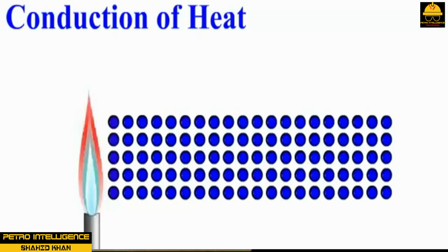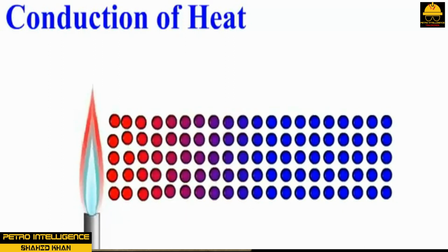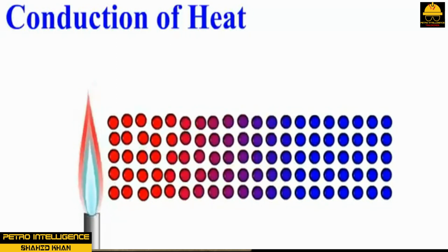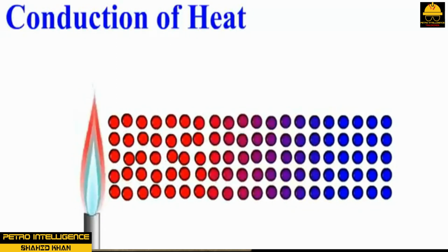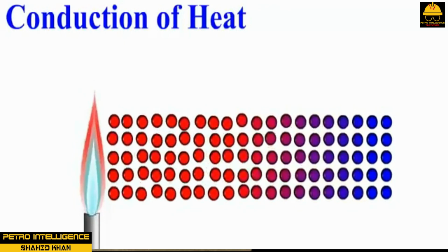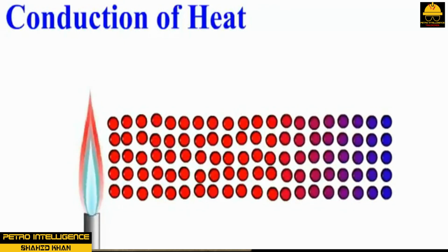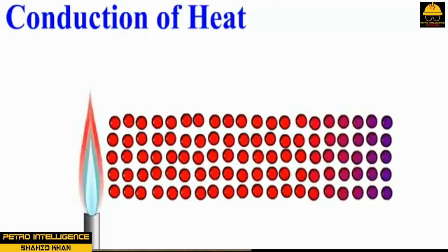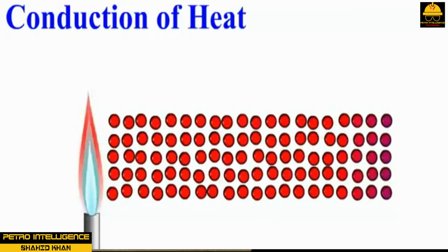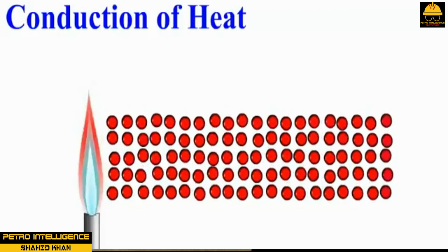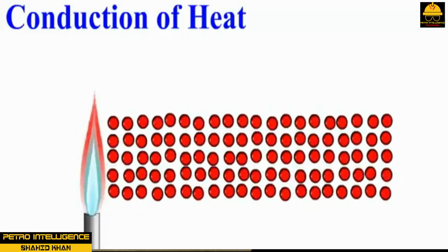Conduction. Heat energy is transferred through solid objects such as tubes, heads, baffles, plates, fins, and shell by conduction. This process occurs when the molecules that make up the solid matrix begin to absorb heat energy from a hotter source. Since the molecules are in a fixed matrix and cannot move, they begin to vibrate and, in so doing, transfer the energy from the hot side to the cooler side.